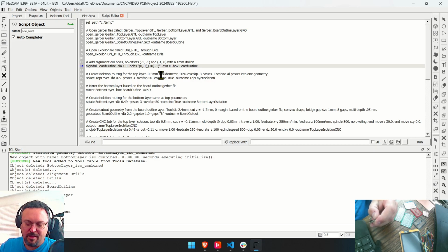It's so easy to align things when you have it close to the origin, because you find where that hole is, and then all you have to do is go up 1 millimeter. Now you're at the theoretical origin, and you set the origin.